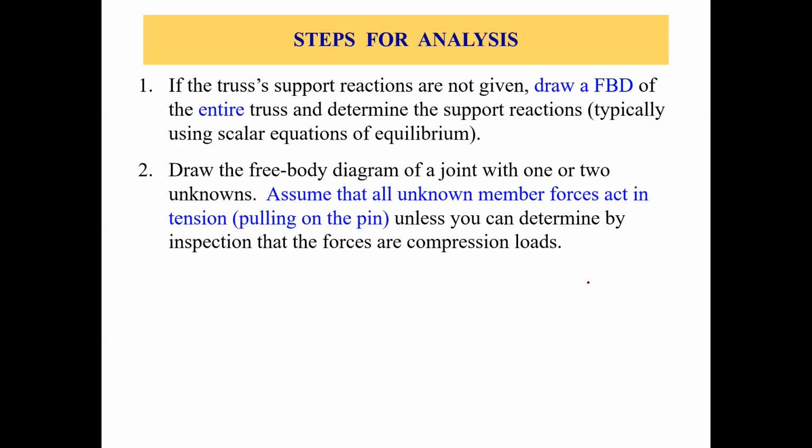Force equations, sigma Fx and sigma Fy. So we can only solve two unknowns, right? If we have a joint with, let's say, three unknowns, can we solve that? No, the answer is no. We can only solve a joint with two unknowns, two unknown forces.